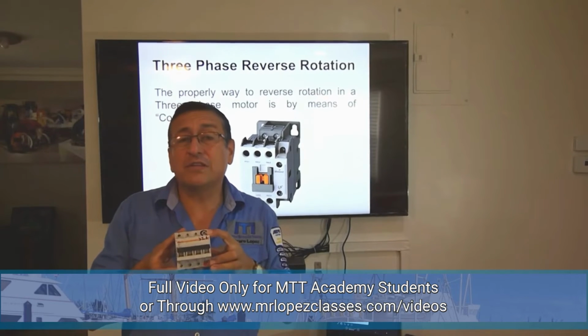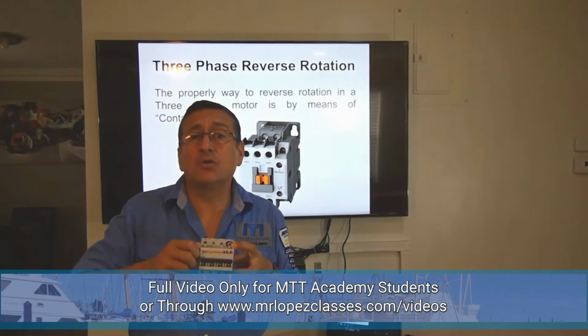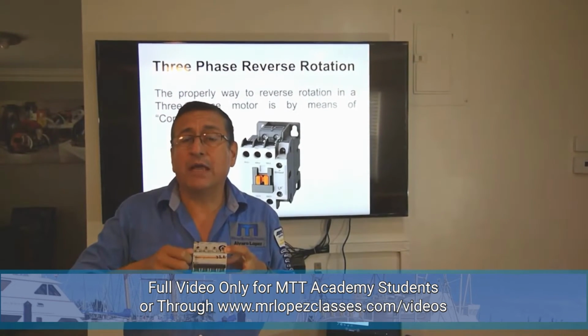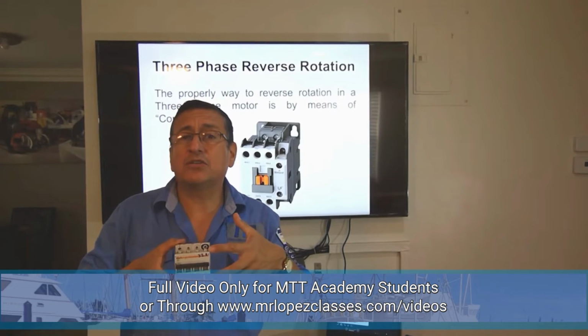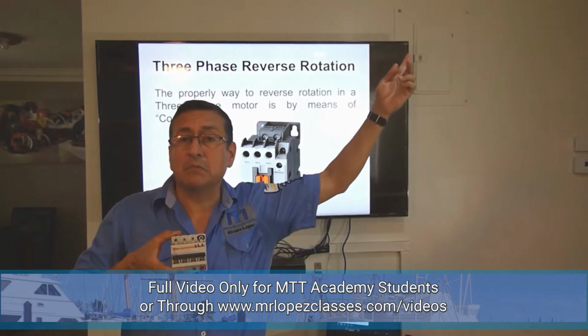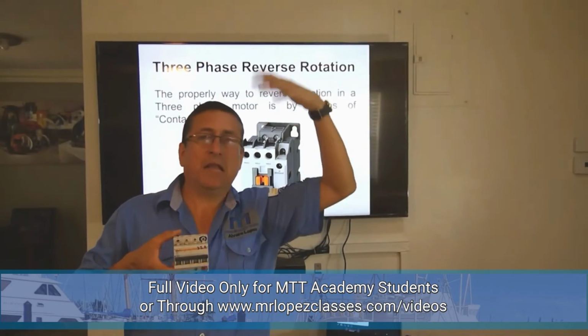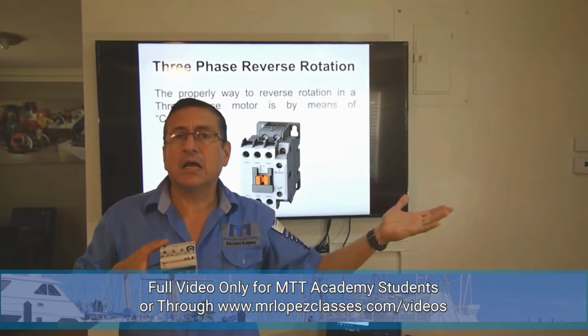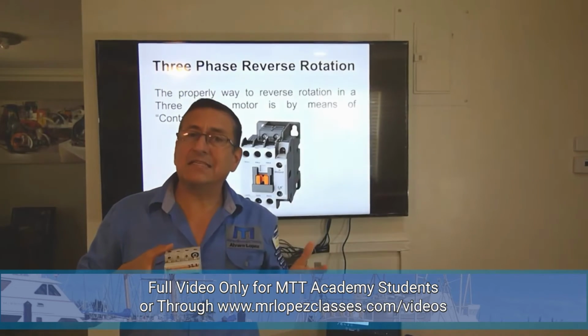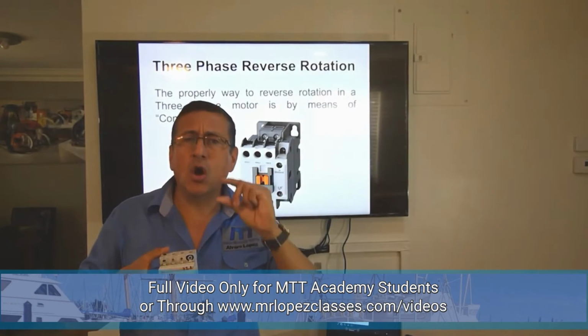What is the function of the signal? Open and close the breaker. Where is that signal coming from? It's a remote signal. That signal, once again, is coming from the flybridge, from the pilot helm, and that signal could be a DC signal or an AC signal, a low current signal.